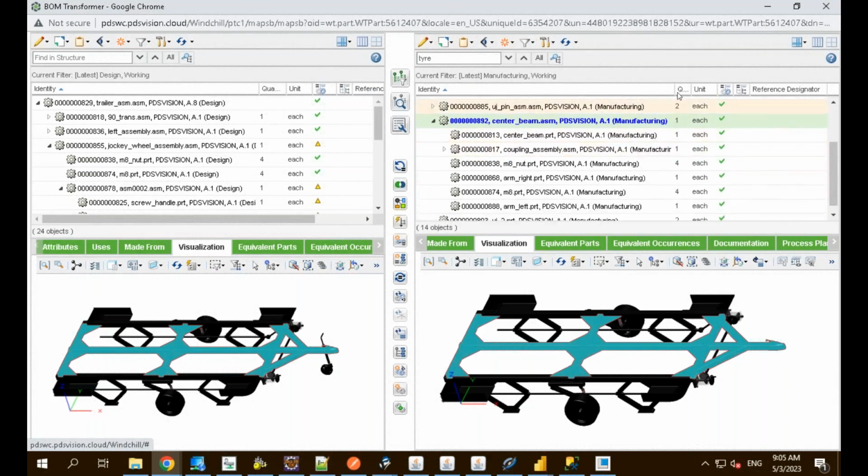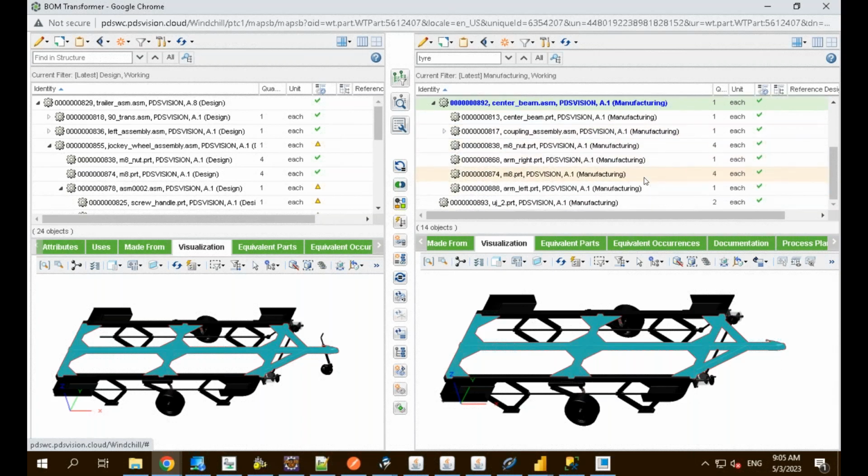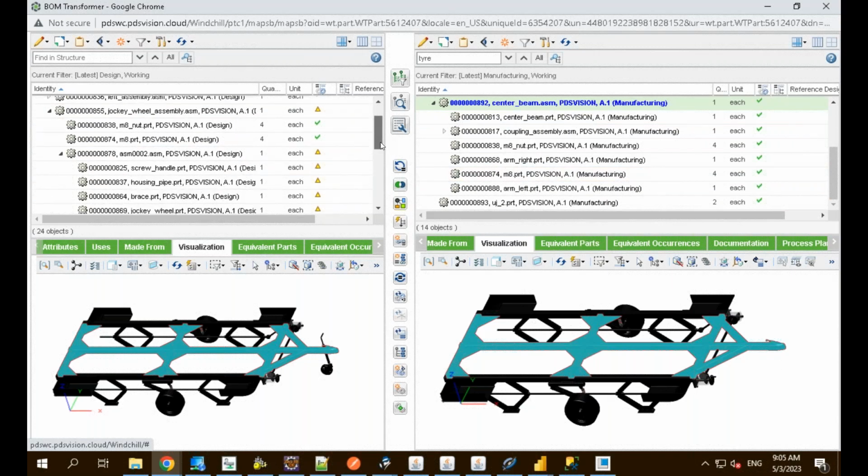you will see everything is created in manufacturing view. Each and everything is created in manufacturing view. That is because we selected the option over there. Out of those 3 options in the drop down, we selected duplicate with propagating. We have propagated everything in manufacturing. So it's duplicate with propagating. So that is how we generate one by one all the remaining components.